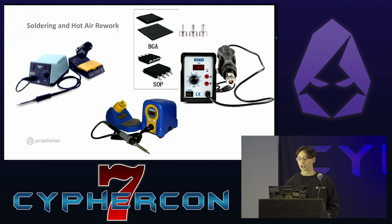I have the picture of two different packages, an SOP and a BGA. You'll notice the SOP has pins on the side of the chip that you can get to with a soldering iron. But for the BGA, instead of having pins, it has a bunch of solder balls on the bottom of the chip, and you can't get an iron down there. So you have to use something like a hot air station to heat up the whole surface uniformly until those will melt. So you can get a nice cheap one. This 858D, there's a million reskins of it on Amazon, AliExpress, eBay, wherever you like to do your cheap component shopping, and all of them work pretty well.